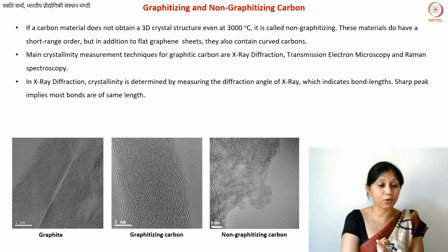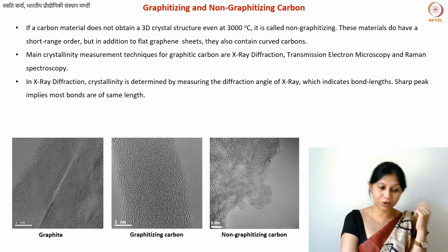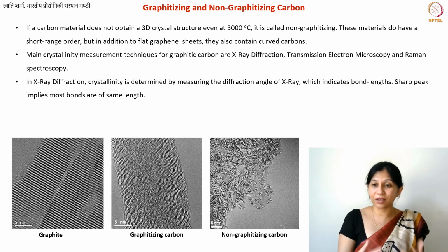Because let's say if you want to do catalytic graphitization, you can add some catalyst which may reduce your final temperature a little bit, but then later on you have to remove that catalyst particle from the material. So you ultimately end up adding one more step. And despite that, you may not really get very high purity in your carbon. So all these things add to the cost, and that is why when it comes to industrial carbon materials, the good carbons are still prepared at very, very high temperatures.